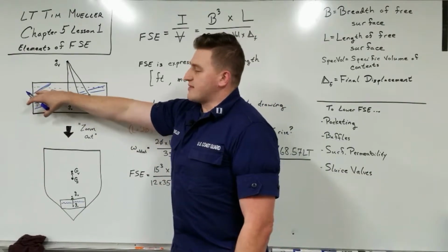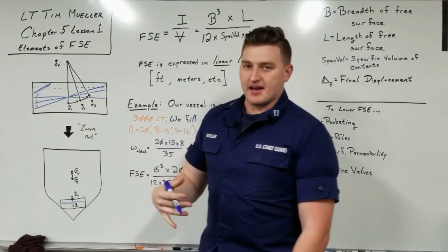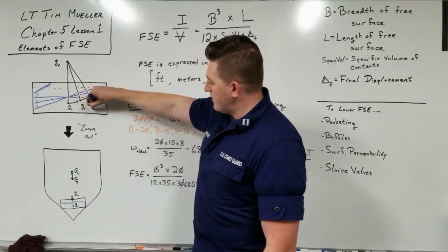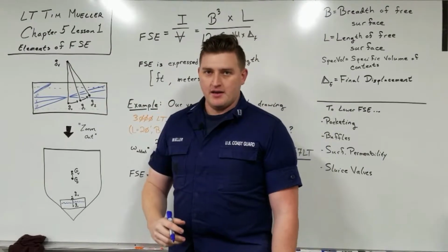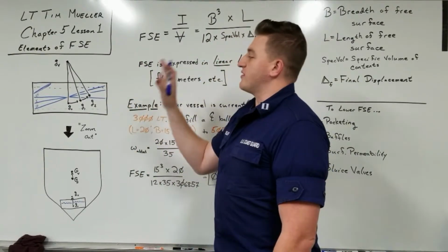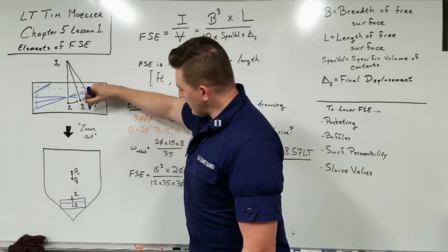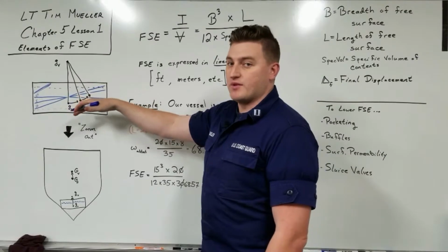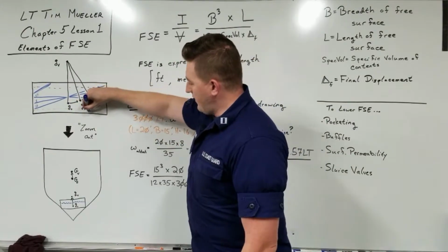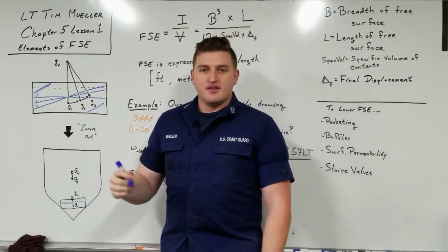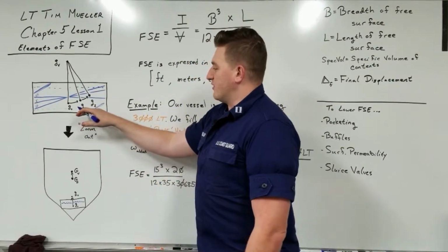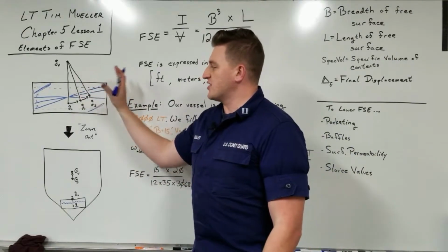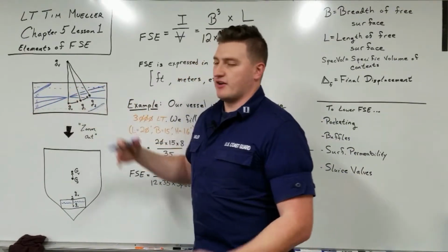So we had this tank full. Now let's empty contents out of it and see what happens. So if we take the waterline to be right here for shallow pocketing, and we tilt over the same angle, the contents inside the tank would settle out right about here. And now this is the same concept. We now have less of a width of that free surface through the entirety of its inclination, whereas here we had very long width.